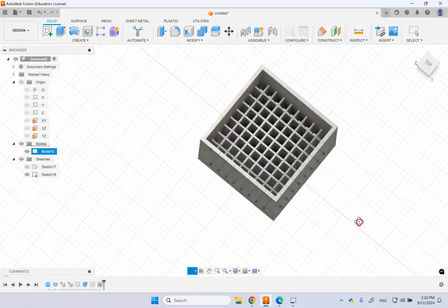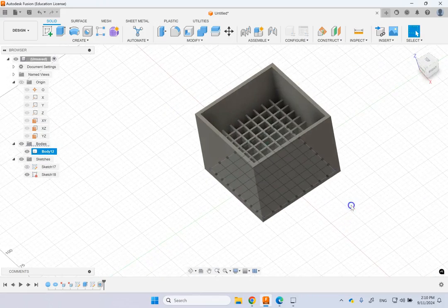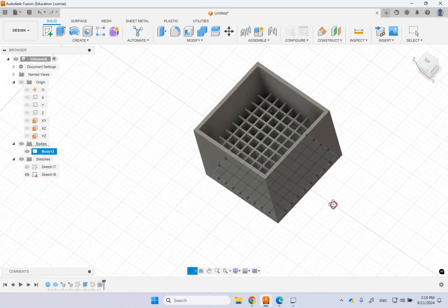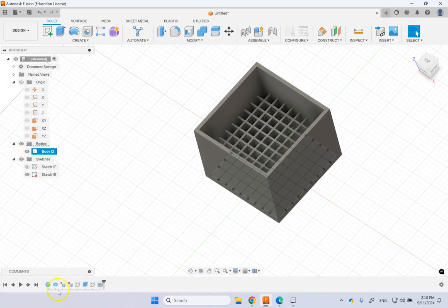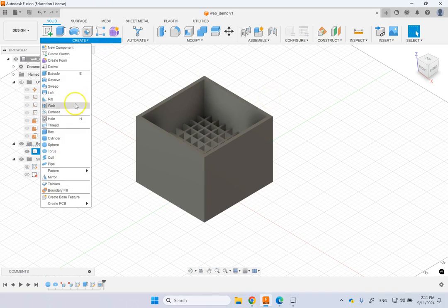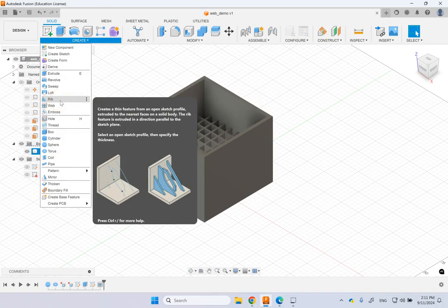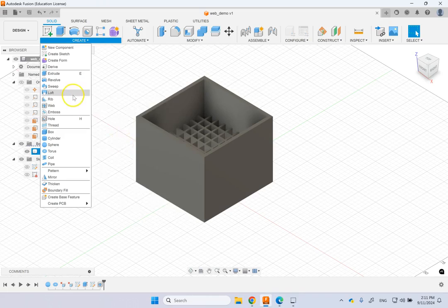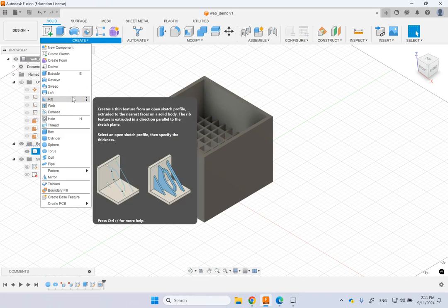Look here. This is the infill pattern just made by a bunch of lines. So you see that is quite a powerful command. Now, rib is typically used as a connection between two walls to act like a stiffener or reinforcement. Okay, so you can have different profiles, and the profile again can be a simple open sketch. It does not need to be a closed sketch. And if it's connecting the two walls together, that's all you need to do.